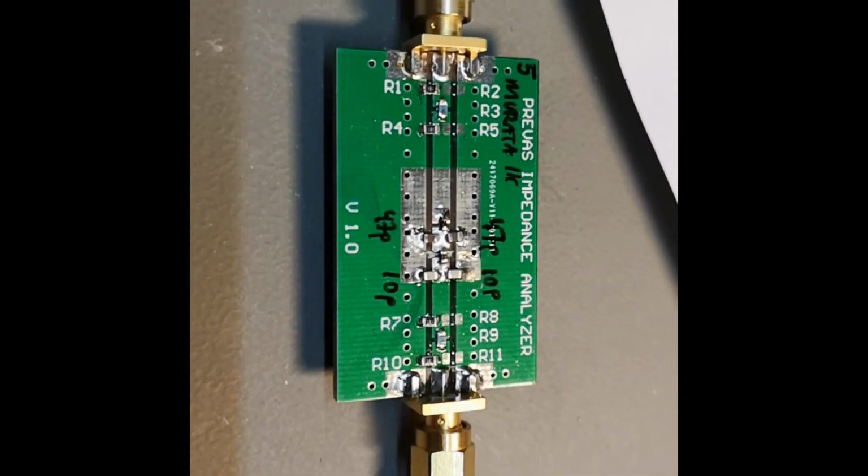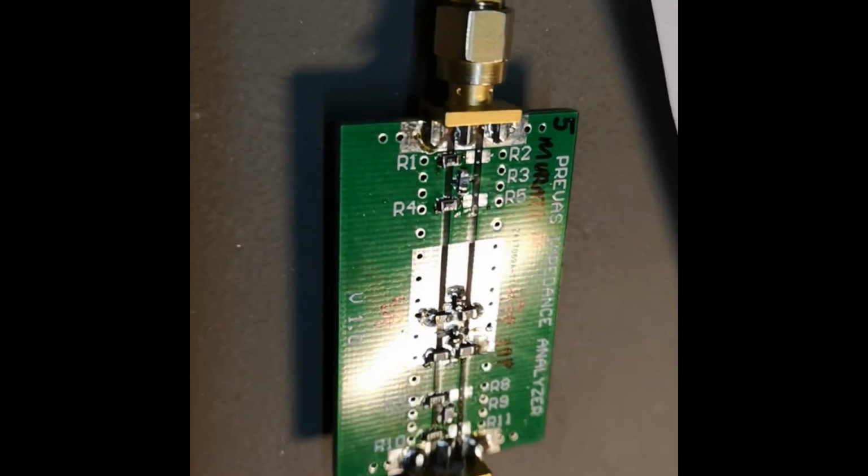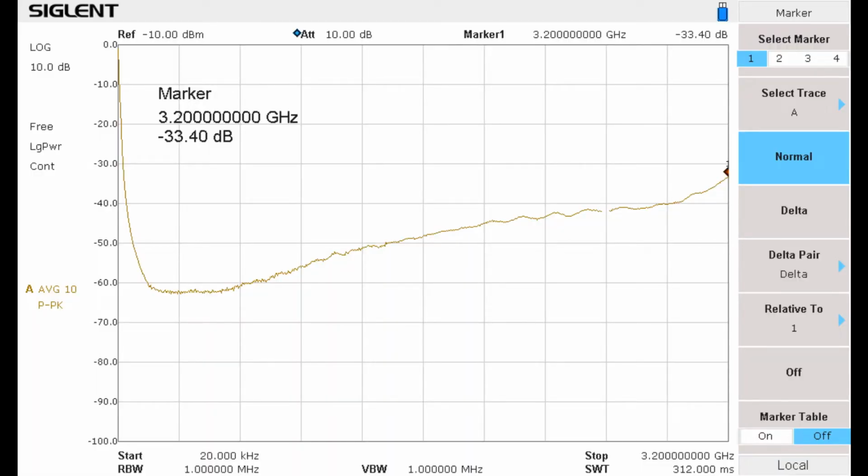So now this is the last curve. This is number 5 again, with the very low capacitor values. And let's see if we are able to do anything good at the really, really high frequencies. And if we look at this curve now, we actually got quite a lot of attenuation all the way up here.